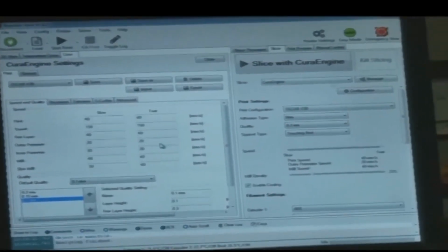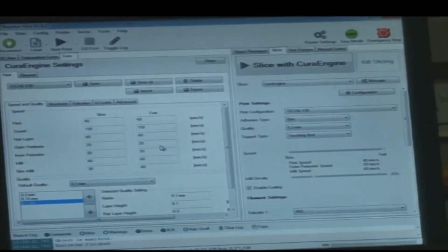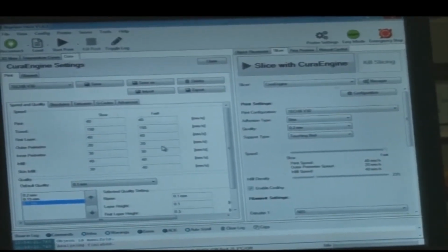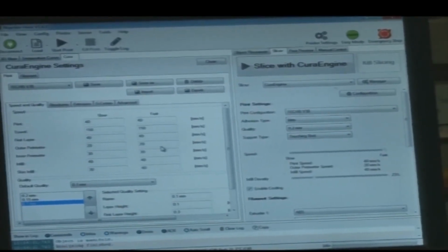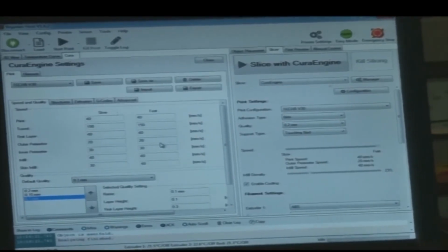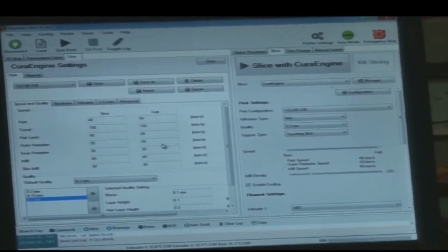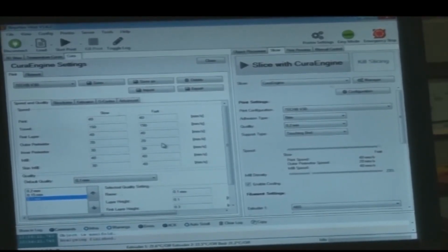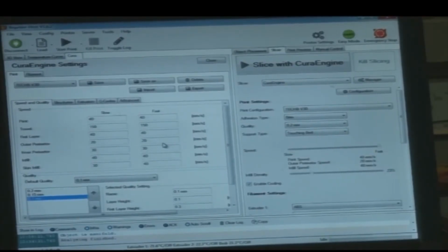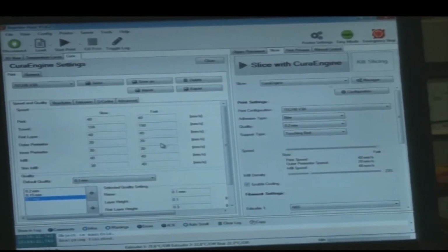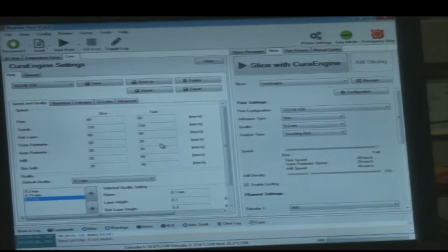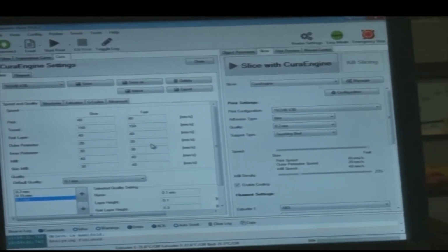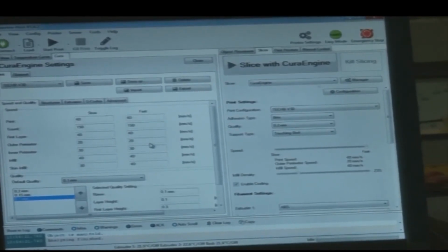This is an important thing to discuss here. If the part is hollow from inside, then we have to be very careful about the outer shell. It is compulsory that the outer surface becomes really smooth and shiny, up to the mark, and the dimension of the profile should be accurate.